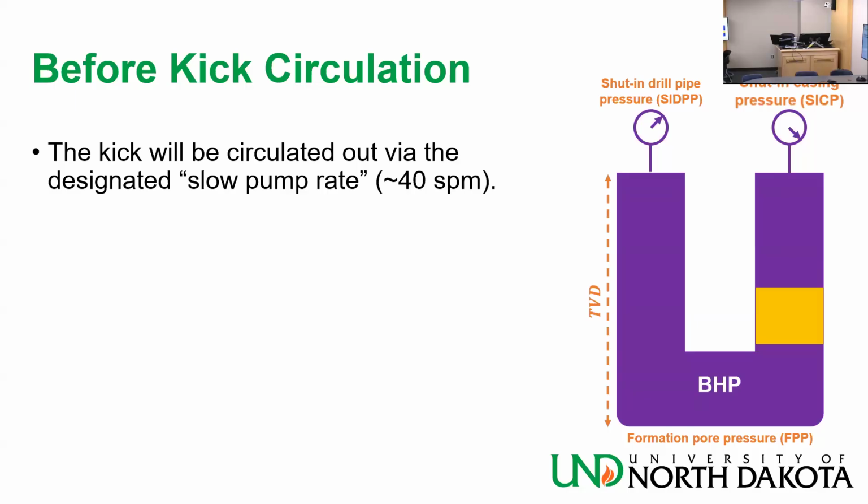You always measure the frictional losses before you start. You just circulate without rotating and wait on the bit, like I did in the first video I showed you when we started drilling. Just circulate and measure the DPP at 40.